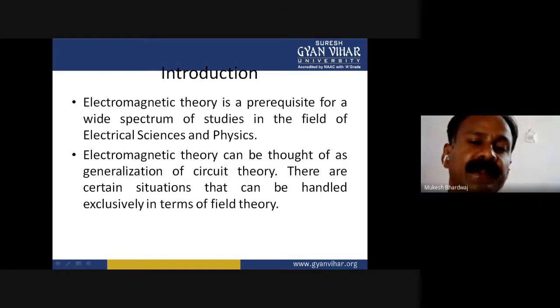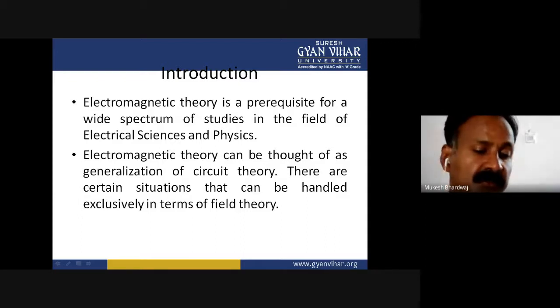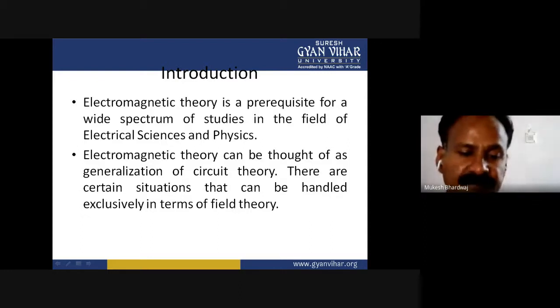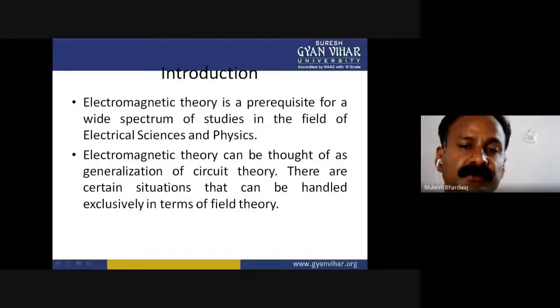Whatever may be the distribution of the charge enclosed, it is assumed that the medium is homogeneous. Then there is Faraday's law of electromagnetic induction and the laws of magnetic force. Similar to Coulomb's law of electrostatic force, the law of magnetic force is given as F equals K m1 m2 upon d square, where m1 and m2 are the pole strengths of the magnets. The phenomenon whereby an EMF, and hence current, is induced in any conductor which is cut by a magnetic flux is known as electromagnetic induction.